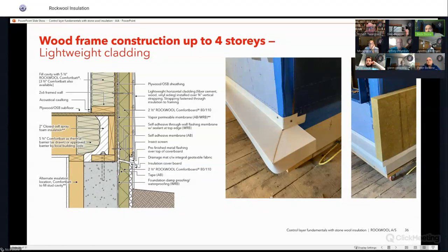What's really nice about Rockwool is the ability for it to cut. And I know you guys will appreciate this. When you go to cut a stone fiber, because it's a stiffer fiber, it cuts more at a 90-degree angle. Versus when you go to cut a fiberglass fiber or a sand fiber, it tends to break and pull apart, and it's not as workable as a stone fiber is.